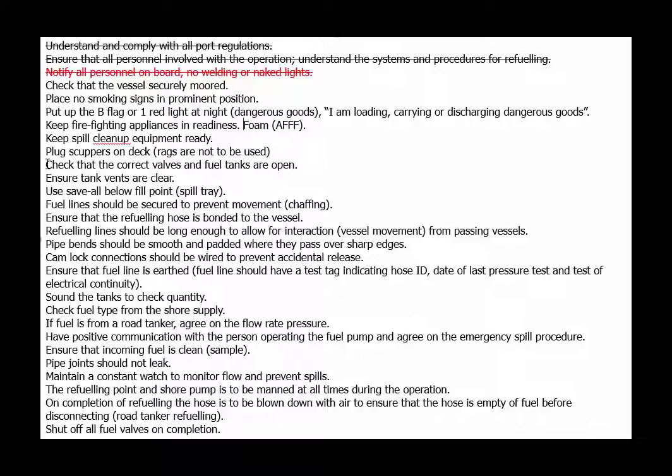Check that correct valves and fuel tanks are open. Yes, we definitely do that, but we're not going to include it in our list. Yeah, vents, we tend to call them breathers, not vents. We're going to check our breathers and make sure that they are free, but I'm not going to include it in our list. Save all below the fill point. Yeah, but we're trying to make it concise. We're going to take it off. Fuel lines should be secured. That one's just obvious. We do need to do that.